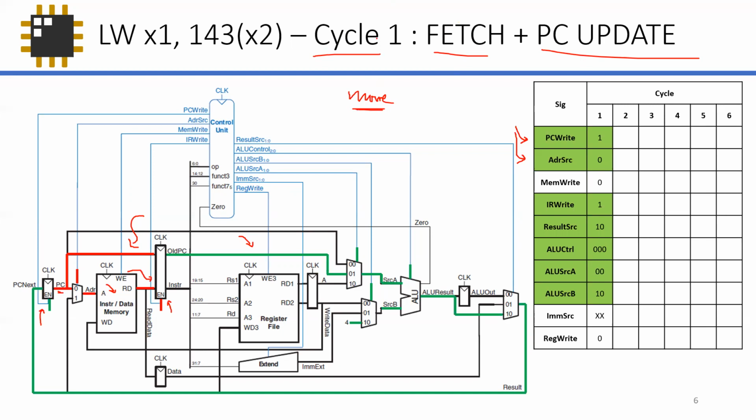And the only thing you have to think about is that in cycle 1 or in state 1, what are the control signals that I need? Right. So we've listed it down here already, totally fine. And because we know that these control signals are important, that's the things that we are going to put in our state machine. Now, if you're wondering, what about the memwrite, IM source, and the readwrite? Well, you have to put them down as well. But let's make the assumption that if it's not written in the state diagram, all other outputs are mostly zeros. The IM source I don't care because we don't need it right now.